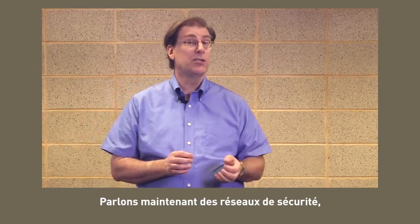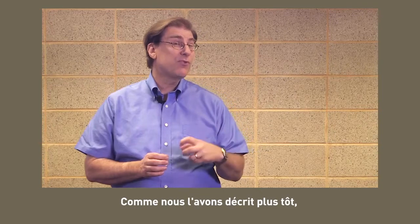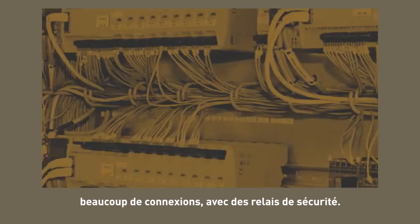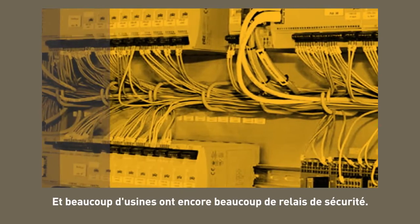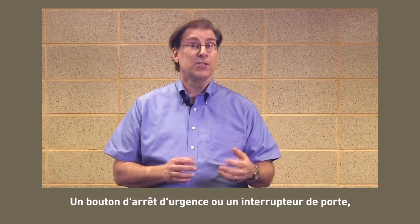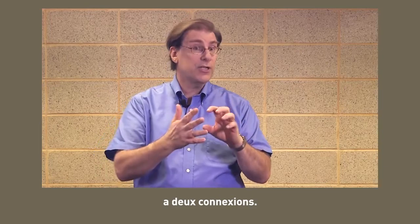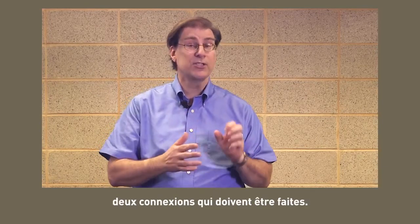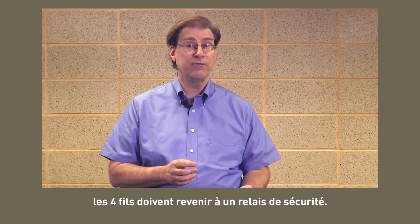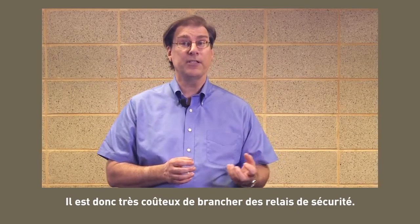So let's just talk a little bit about safety networks because you're going to hear more about that. Just as we described earlier with all the I/O with lots of wires and lots of connections, they had safety relays. And a lot of plants still have a lot of safety relays, but that's a single point connection. So like an e-stop switch or a gate switch has two connections. Each time you push it, you have two connections that have to be made. That means all 4 wires have to come back to a safety relay. So really it costs a lot of time to wire in safety relays.